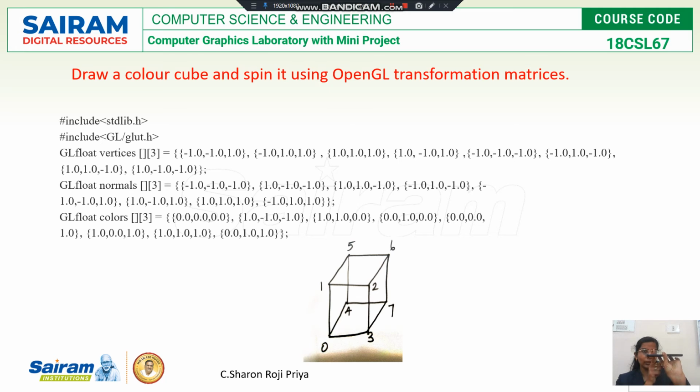If I am viewing this left side, exactly behind the left side is my right side, so right will become invisible. Similarly, if I am viewing this top, exactly below this top is the bottom. If this is visible, bottom will be invisible.